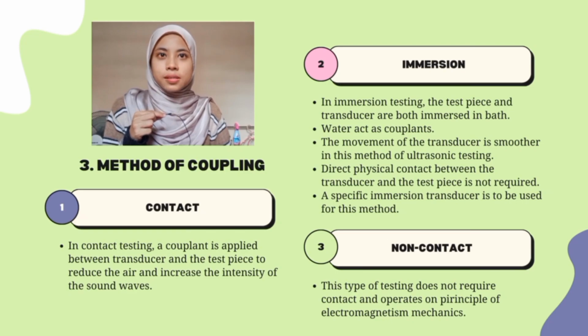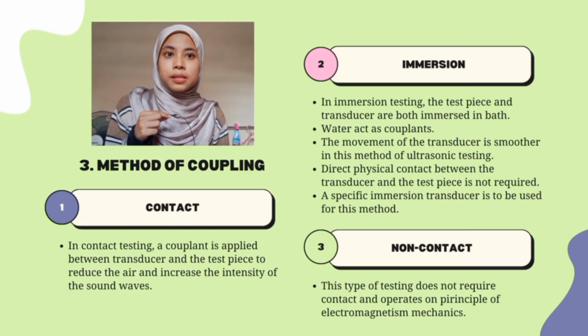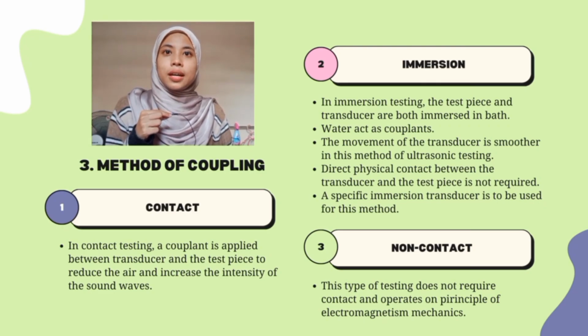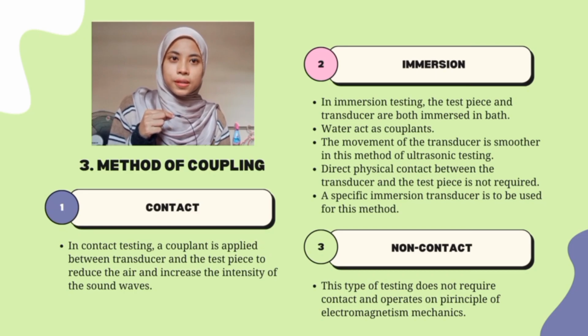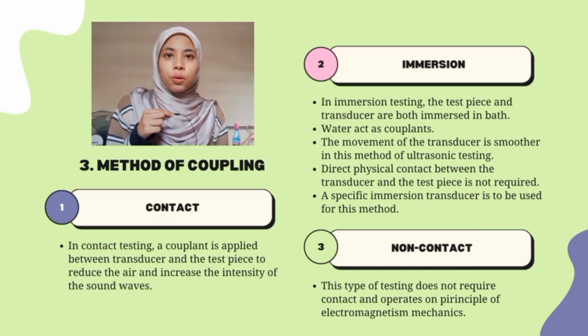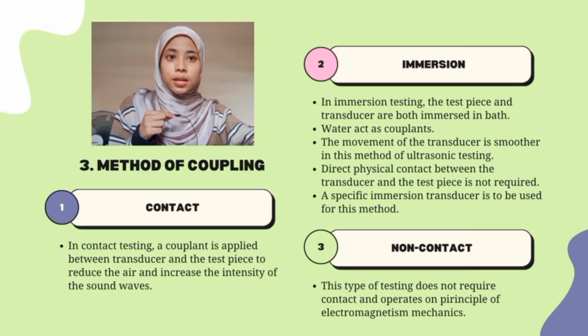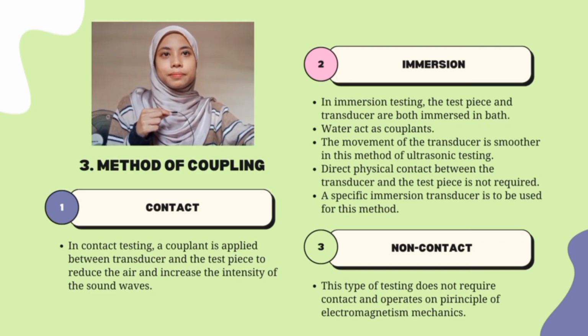In this type of testing, the water acts as the couplant, and the movement of the transducer is smoother in this method of ultrasonic testing. Direct physical contact between the transducer and the test piece is not required. Also, a specific immersion transducer is to be used for this method.